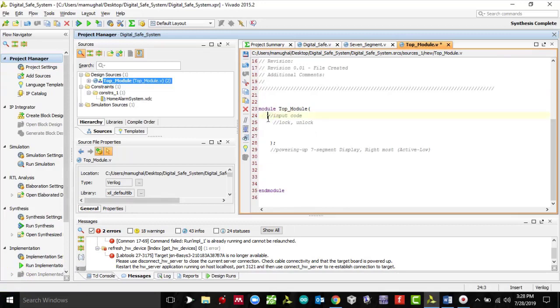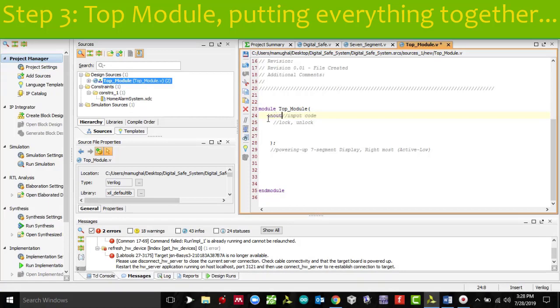We'll start with our port identification, input. Remember, it's a 5-bit code, so we would need 5 switches to declare the code. So let's declare them as an array. And I'm just going to use the variable SW because that's how the Basys 3 constant file by default names the switches. So we don't have to make that change in the constant file. So that saves a little bit of time.